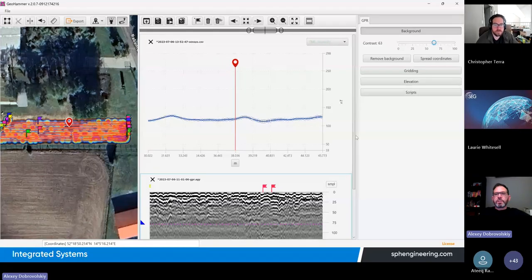Why is it useful? Of course, you can check the quality of GPR data right in the field without the use of any complex software packages. My strong belief is that if you don't see anomalies in GPR data without any extra processing steps, that means that most probably you need to repeat data collection, or GPR will just not work in that area. For example, if it is covered with clay.